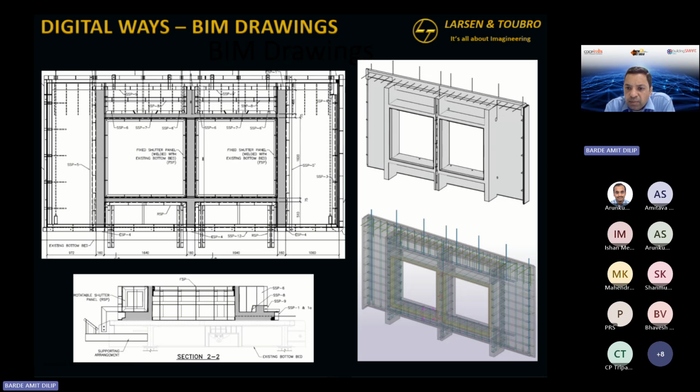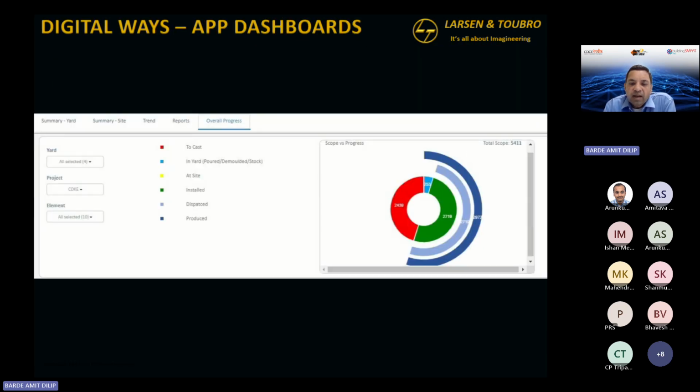Even a 6 mm link is modeled. The quantity control is better. Quantity takeoffs are better, and we are able to generate them quickly. The joint grouts, a lot of precast is a very complex system, right? It's not just pouring concrete and steel. We have to account for how many couplers there are, how many specific connectors, how many joints, what is the joint grout quantity and all. If a cast-in-place BOQ will have 10 items, a precast BOQ will have 50 items. So that gets tracked well.